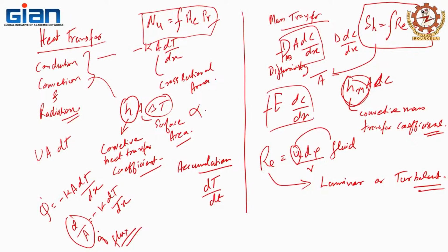Okay, do you remember a term called alpha, which is your diffusivity? What is the equation for alpha? I'm so sorry for putting you on the spot, but do you remember? You have your K over rho Cp, so rho is the density of the material, Cp is the heat capacity of the material, and K is the conductivity of the material.